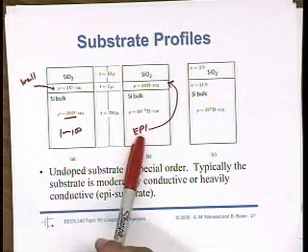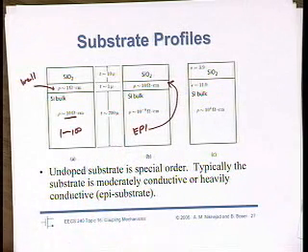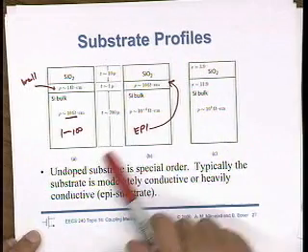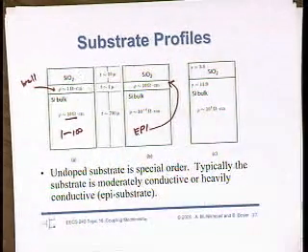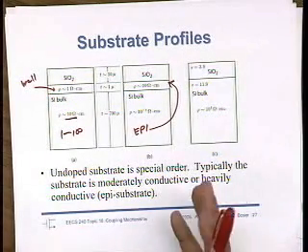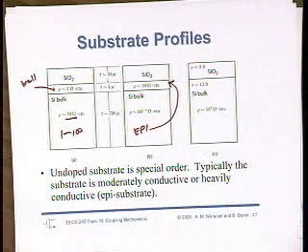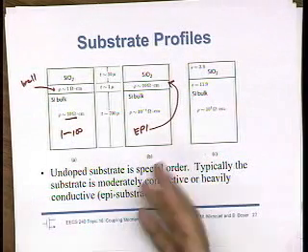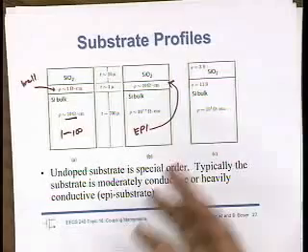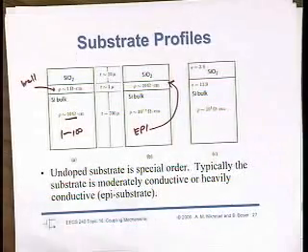There aren't that many times when you think about the substrate, right? What's one instance where you have to worry about substrate currents? Latch up? Yeah, latch up. So who here has heard of latch up before? Okay, so you guys have heard of latch up. If currents flow in the substrate, right, you get resistive drops, and those resistive voltage drops could potentially turn on and off junctions. If those junctions turn on and you start injecting minority currents into the substrate, you get latch up. And we'll talk about that a little bit next lecture.